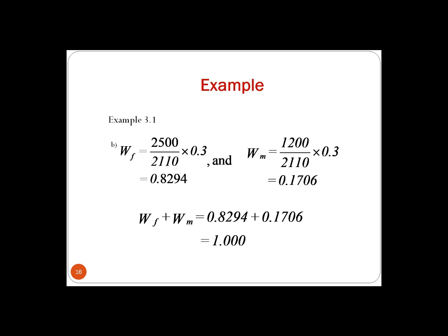Now similarly we can calculate the capital WF. It means the weight fraction of fiber and the weight fraction of matrix, and the sum of these two, WF and WM. And obviously this must become unity in order to verify the weight of the composite.